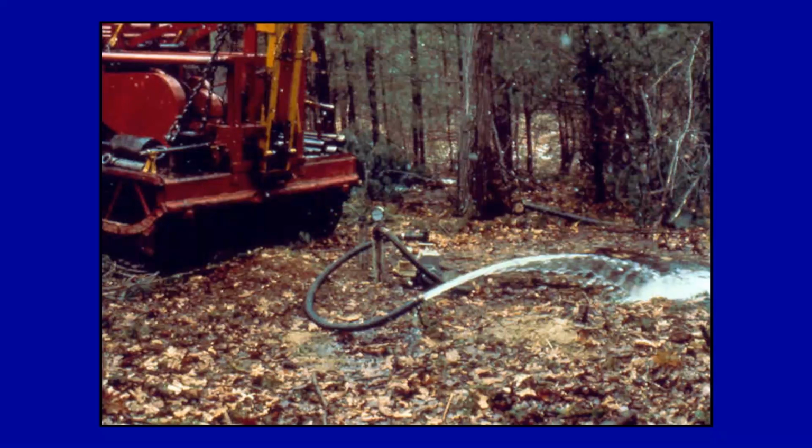Of the two wells, whichever pumps the higher capacity, we will then run a pumping test of 2 to 4 hours in duration, noting the GPM of the test well, the inches of vacuum, and the drawdown within whatever has become the observation well.